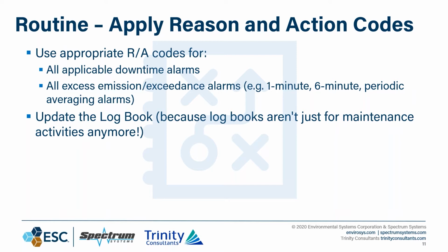I've been to several facilities where they've got a control room logbook, a CEMS shack logbook, electronic logbooks, and also logs sitting in the maintenance management system, where stuff did not match across the board, or information for CEMS only occurred in one of those logbooks and not necessarily in the CEMS shack logbook. So make sure your logbooks are up to date and that you're addressing these alarms in real time, because if I'm coming to audit your system, I'm going to look at the time code for that particular alarm and gauge your response based on your logbook entries.